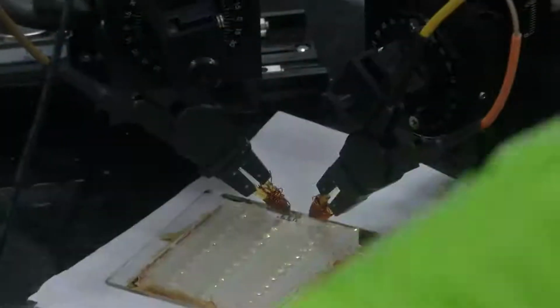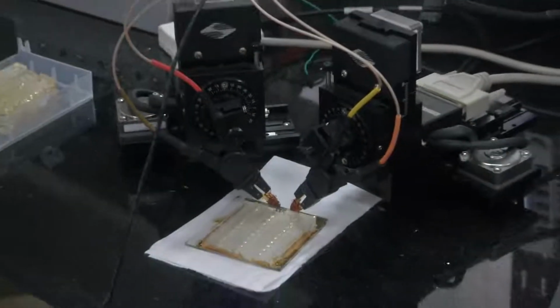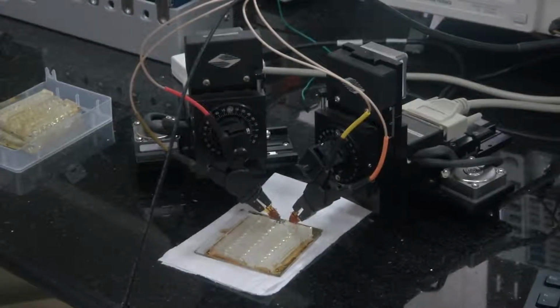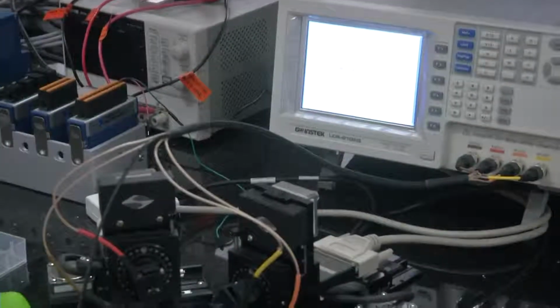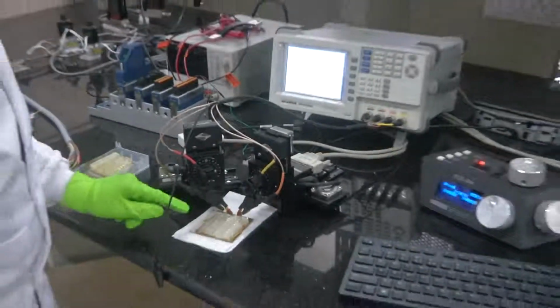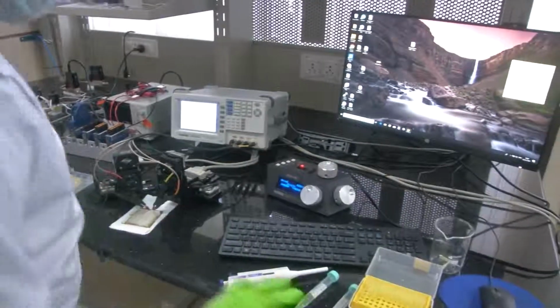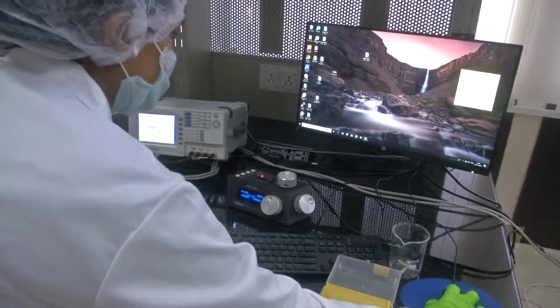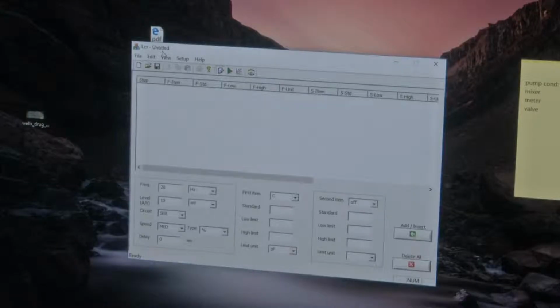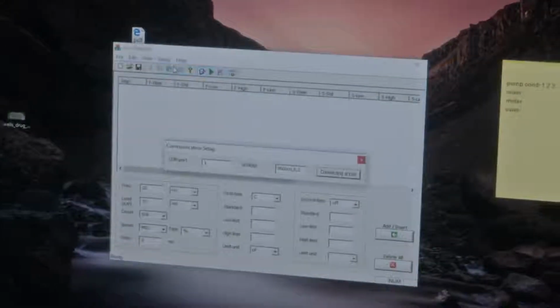Now let's use the software to see, over the frequency sweep, how we measure the impedance of this. Now the well is empty, so just the bare resistance. Let's see what impedance can be seen in the software. Initially we've taken care of the calibration, open circuit and short circuit calibration, of the two sensing electrodes we will be using for measurement. And once calibration is done, in the measurement phase after connection, we'll have to connect to the COM port.